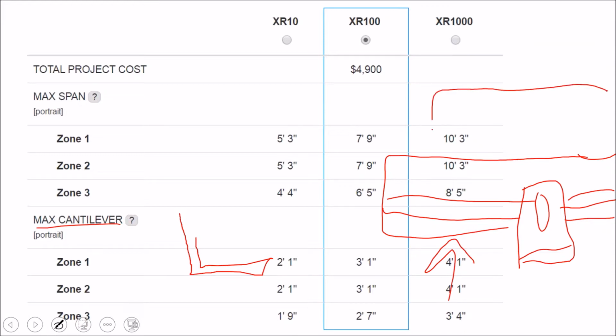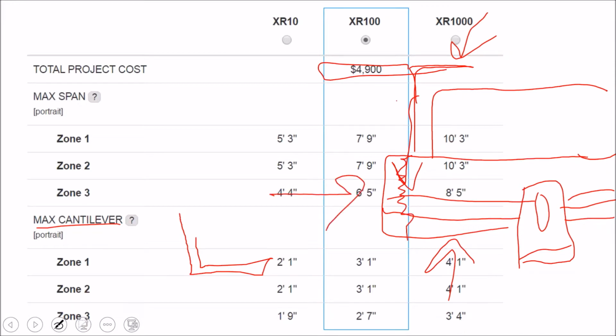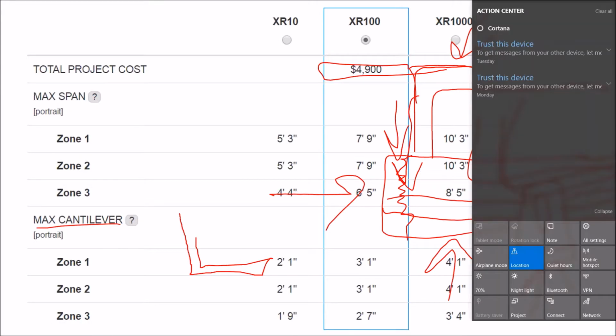Here's the edge of your solar panel, and at the very end there's a bolt that goes down into the end. The clip only has one kind of flange on it, whereas in the middle it would have two flanges. So you'll put your last clip on, and then take a Sawzall or a reciprocating saw and saw off the remainder of the rail, and then put a little cap over the remainder of the rail. That way, your attachments and all your wires and cabling are hidden underneath the solar